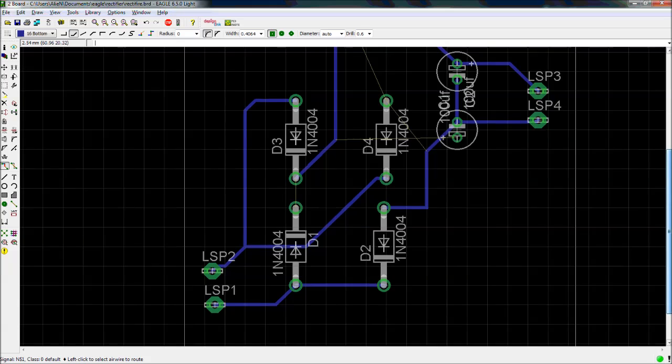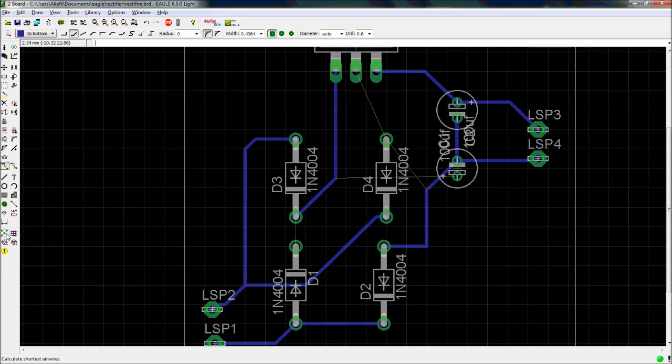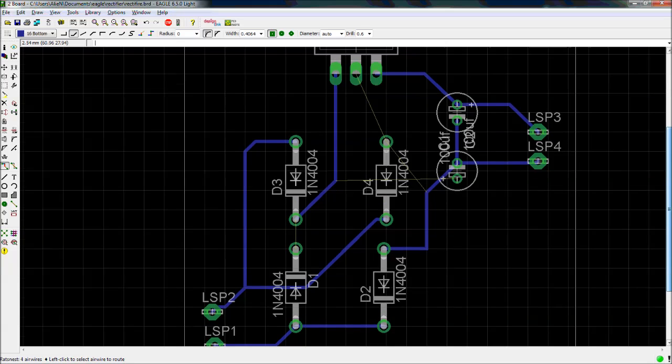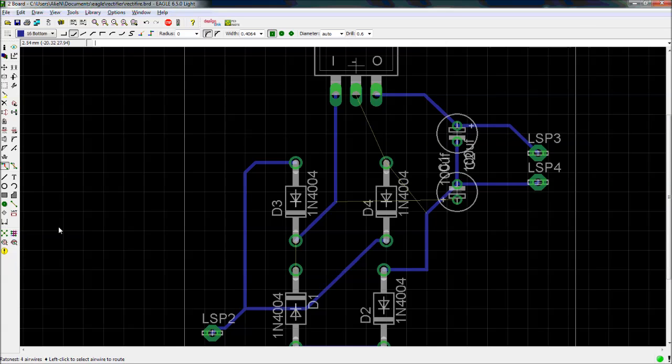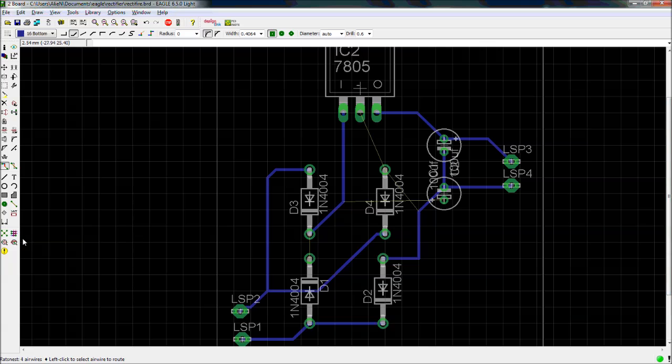You should frequently hit the ratsnest button because it will bring out the hidden ones also. If you connect some wire and another wire gets hidden, then it will be very difficult to visualize. So frequently use this ratsnest button.